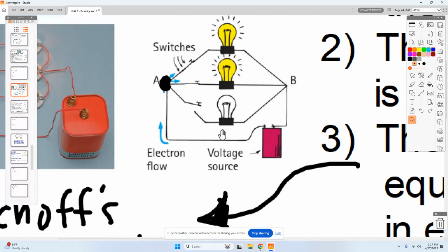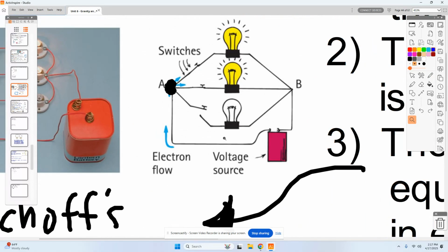In that particular junction, I see 4 wires coming in. If you're connecting this up with a series of circuits, you might have 4 wires all connected together. Let's say that I have 3 amperes flowing through here, coming from that battery. I have all these branches that the current could flow through. I see one of those light bulbs has an open switch, and so no current is flowing through there. But let's say that I have 2 amperes flowing through here. Could you reason through, using Kirchhoff's current law, how much current must be flowing through that top light bulb? It'd have to be 1 amp.